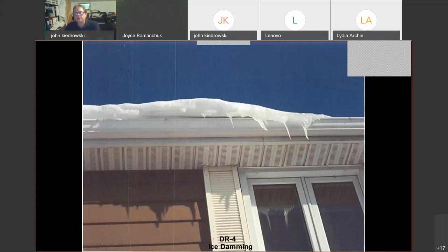Well, ice damming isn't too bad, but imagine where these sometimes go down probably halfway, if not past the windows. So this is a sign of, again, insulation and the clear ventilation over the top of this exterior wall in the actual roof attic space.